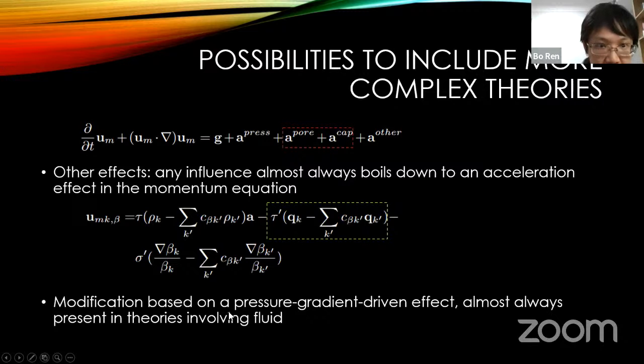On the other hand, regarding these modifications, I just mentioned that I used Darcy's law's value, which is proportional to the pressure gradient inside the solid region, to modify this drift velocity inside the solid region. If you are facing other physical laws in other physical regions, any set of physical equations involving fluid almost always contains a pressure gradient driven effect.